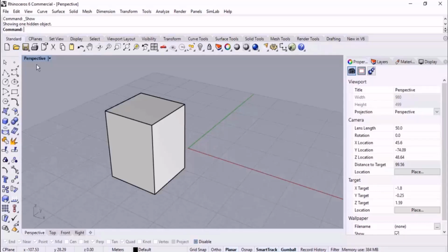Or other examples, save, as I told you before. Check out the icons, save and export selected objects. Most of the tools offer two commands by using the left and right buttons of the mouse, like trim and untrim, or split and split surface by ISO curve. But some of them have only a single capability, like this, circle center radius. But most of the tools give us two different kinds of commands by using the left and right buttons of the mouse.